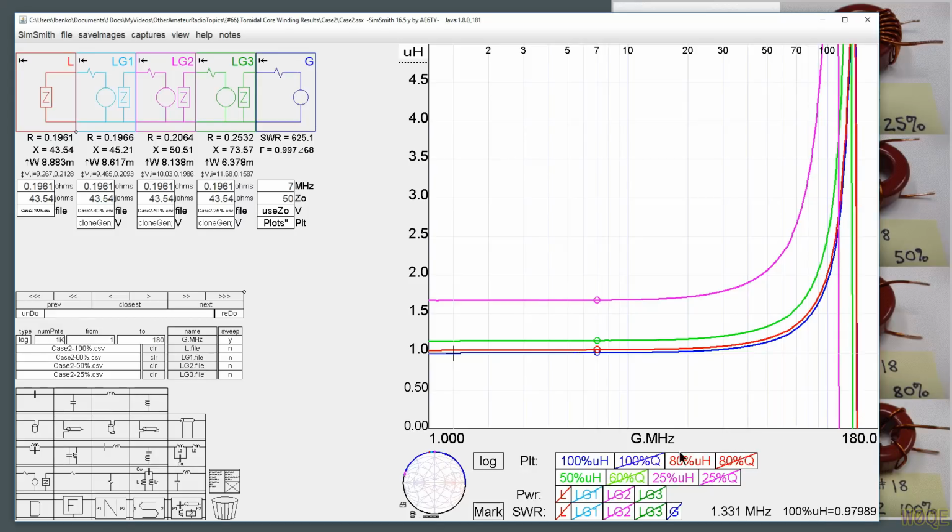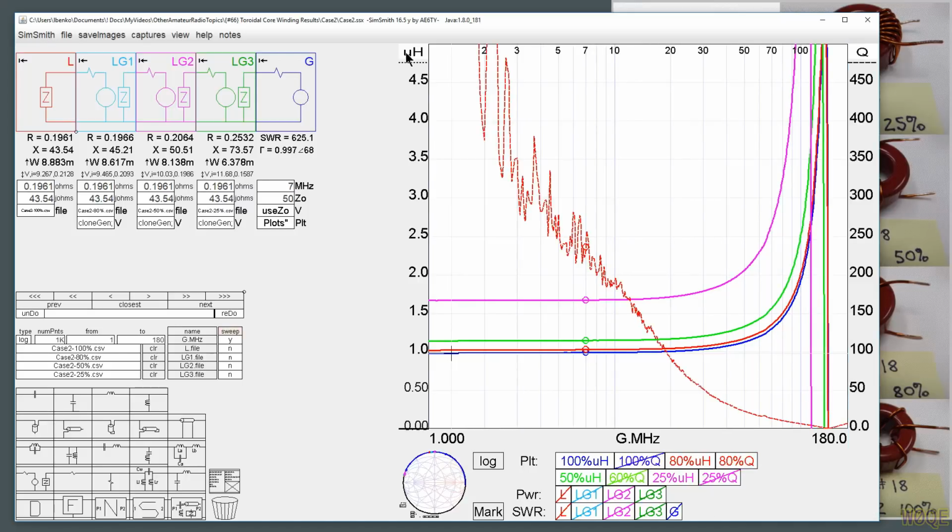And if we look at the Q, if we call the 80% Q the standard, using 100% of the windings shows the Q, in my opinion, to be maybe a little bit higher than the 80% Q, not much. The 4170's got a lot of noise here, and if you realize what's going on, you're trying to measure an impedance that's incredibly tough to measure. You're measuring an impedance that's got a reflection coefficient that's 0.99, maybe even 0.999, and it's just hard to do